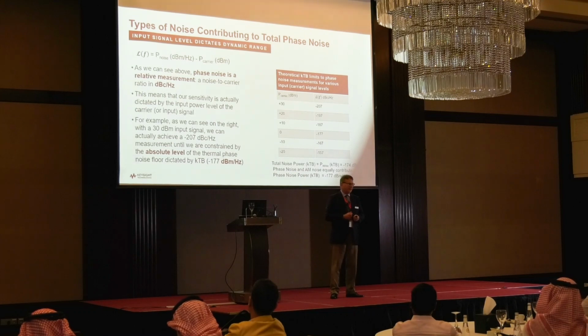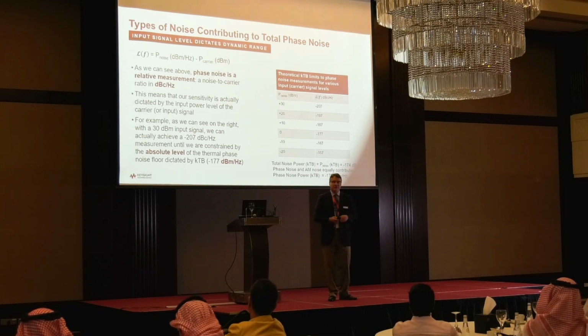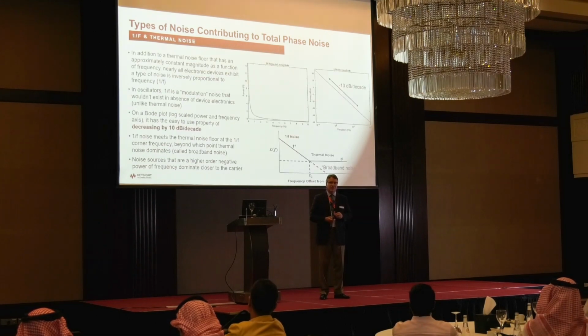And we have already done tests in our lab where, if we have a 1 watt transmitter that's exceptionally clean at far offsets, we might have a phase noise of better than minus 180 dBc at far offsets as an example. So extremely high dynamic range is possible if you have a good receiver, a good system. So that's a quick overview of that.